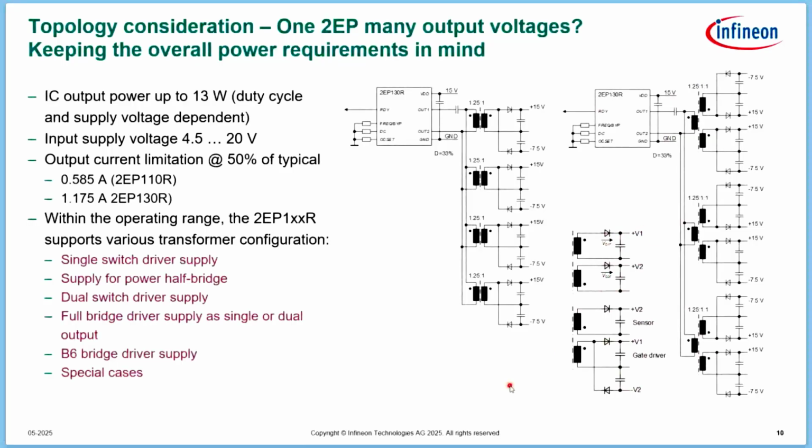The IC itself doesn't really care how this energy is distributed as long as the series capacitor is there. The symmetric approach will occur in the transformer and then avoids a saturation of this transformer stage.